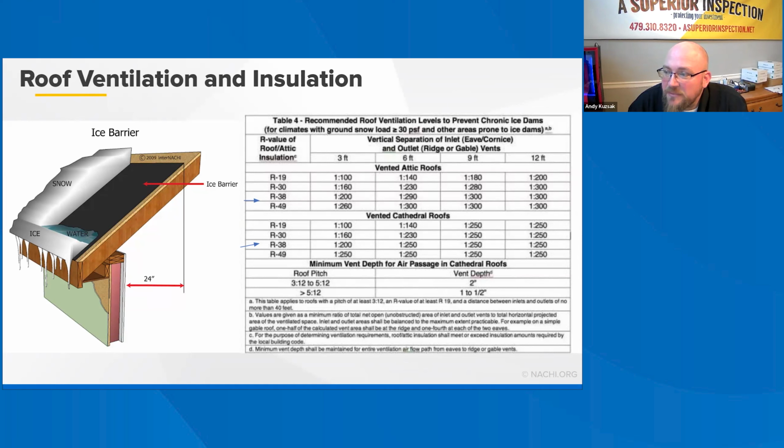Ventilating roofs in extreme hot and humid conditions may add rather than remove moisture from attics and enclosed roof spaces. However, not ventilating roofs may void the asphalt composition roof manufacturer's warranty and slightly decrease the life expectancy of the roofing material due to increased temperature of the roof surface. Other tile, concrete, and metal roofing materials would not be similarly affected.